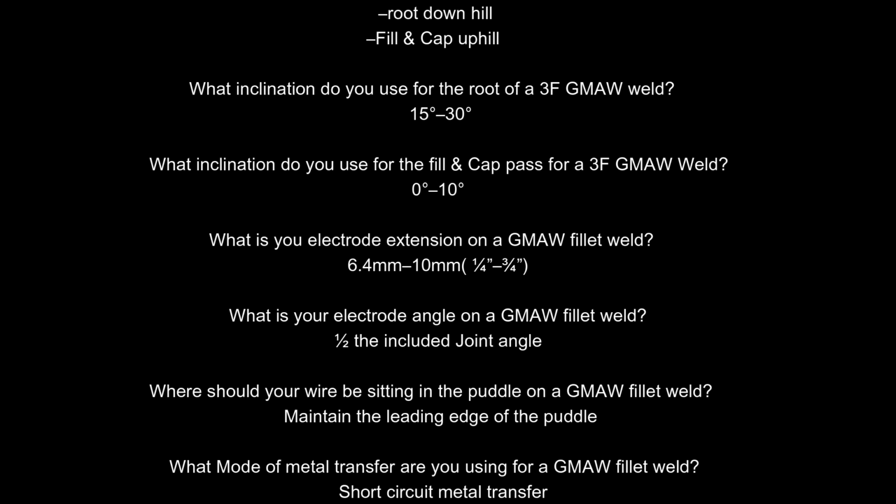Where should your wire be sitting in the puddle on a GMAW fillet weld? Maintain the leading edge of the puddle. What mode of metal transfer are you using for a GMAW fillet weld? Short circuit metal transfer.